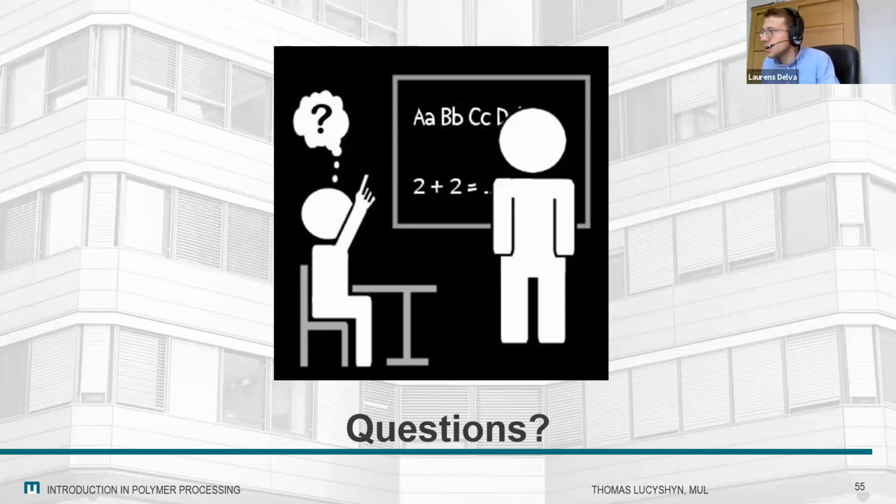Perhaps a last question from Roberto: why can't thermosets be mechanically recycled? Yeah, the problem is that you cannot reshape them. You can grind them, you can cut them down to small pieces, but you cannot remelt them. They're not deformable anymore. Once those bonds are established, especially for the duromers, they are not reshapeable anymore, because that's the principle for thermoplastics: you always have those entangled structures, you melt them and then they become movable, flowable. If you have these fixed bonds, the shape is given and you cannot change it anymore.